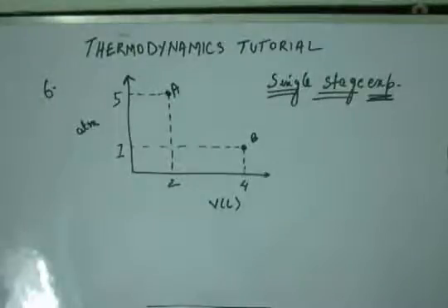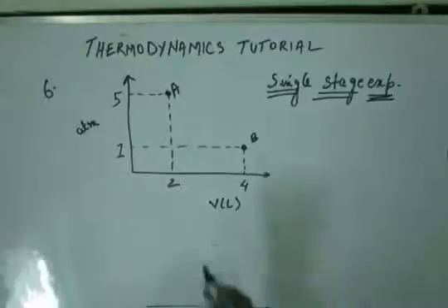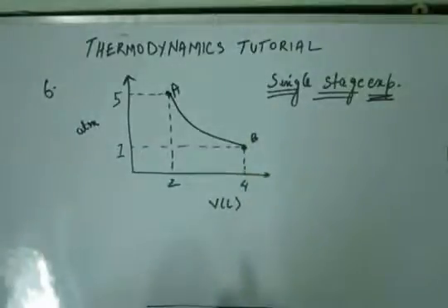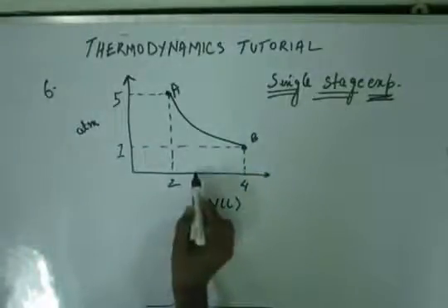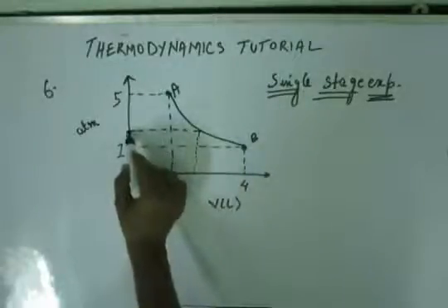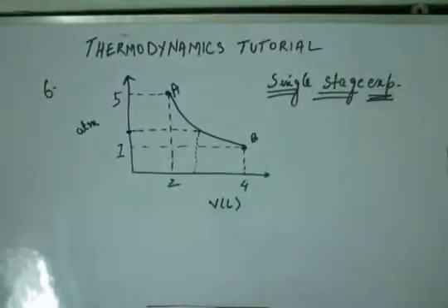Now as you can see, in all these dotted lines shown in this graph, I have not joined A and B by any path, because I cannot do so, because it is a fast process. So at any moment during the process, pressure is not completely defined inside the volume, inside the system. So I cannot show any point on this graph, because if I plot any point, suppose for the sake of argument I show the process like this, that means I am very sure that at this volume the pressure was this. So I have a unique pressure corresponding to every volume, but that is not true.